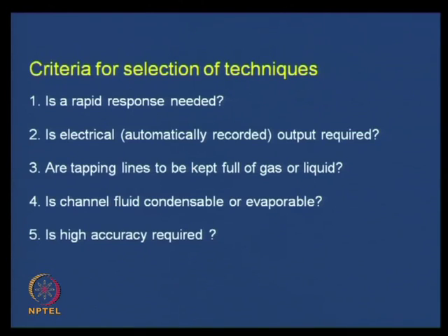And if we have gas filled lines, special cases, we can go for inclined manometers or micro manometers. Remember this: using manometers, if we need high accuracy, then instead of liquid mercury manometers, we can go to liquid gas manometers for liquid filled lines, and for special cases where we use gas filled pressure lines, we can use inclined manometers or micromanometers.